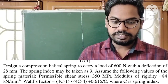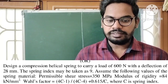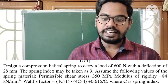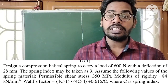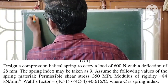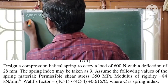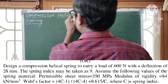And Wahl's factor is equal to (4c minus 1) by (4c minus 4) plus 0.615 by c, where c is spring index. So here we have to design a compression helical spring.